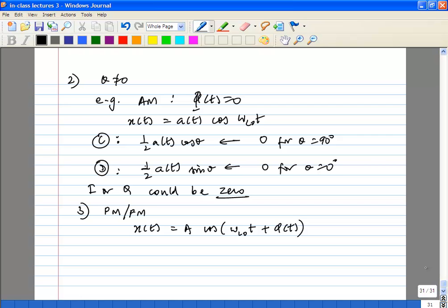If you use just the I and Q channel, there's an inherent phase error which exists between the incoming signal and the LO. That's right. It's inherent and it's arbitrary. You never know. Once you are locked in the PLL, then you can try to track it. You can try, but there will always be some phase error between the two.